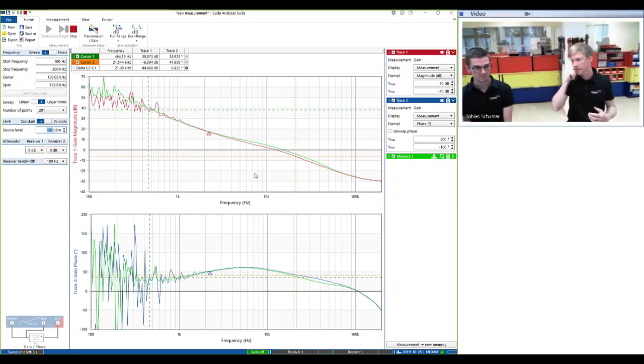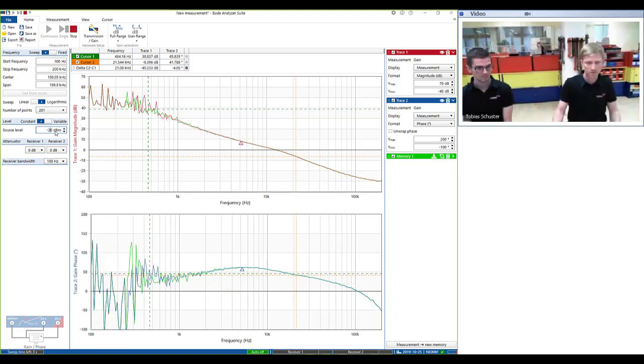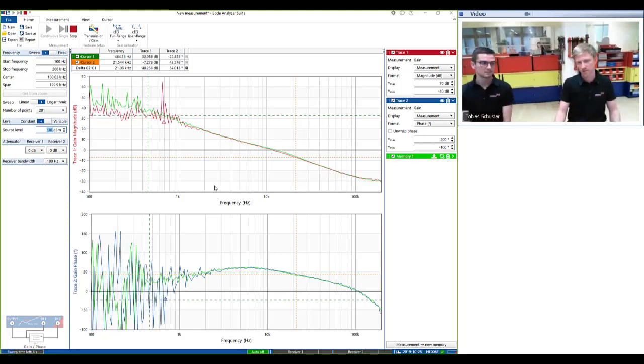We are in an operating point where the system seems to be pretty sensitive to the injection signal level. So it has still changed. We need to further reduce it. I update the memory and I reduce it to -30 dBm. And now we are at the minimum voltage that we can apply in that case. And now the result did not significantly change anymore.